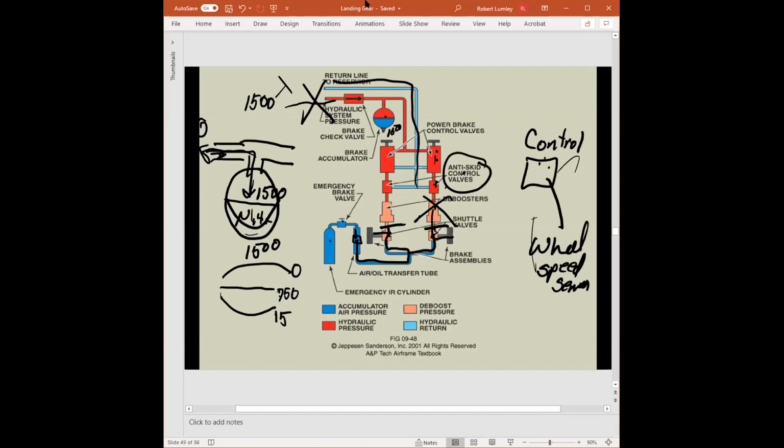So once the emergency brake valves are actuated, eventually, when the aircraft stops, the wheels will lock, and sorry to say, the only thing you can do is shut off the valve here, and then bleed off the system itself to be able to move the aircraft, and then go through the maintenance manual as far as resetting everything. Are we good there? That seems like a lot of work, but yes, we are.